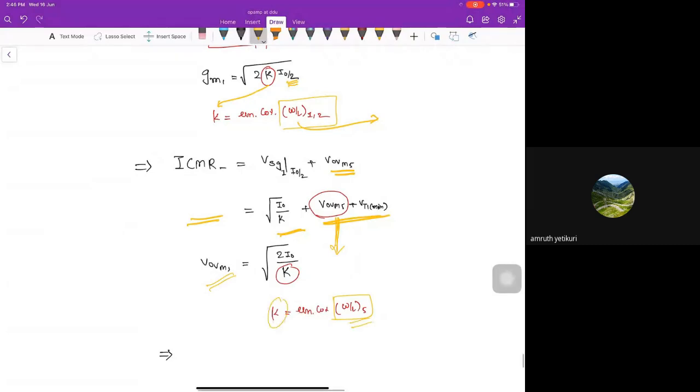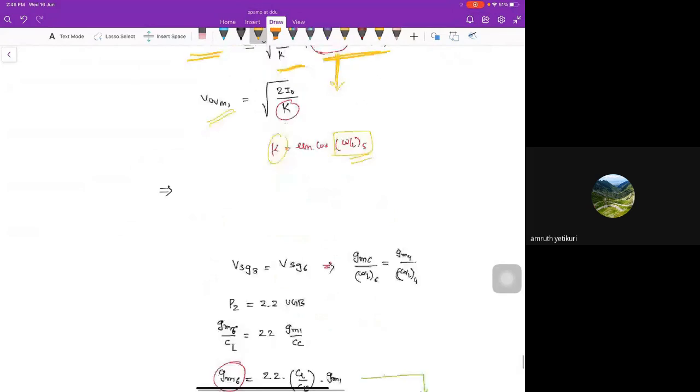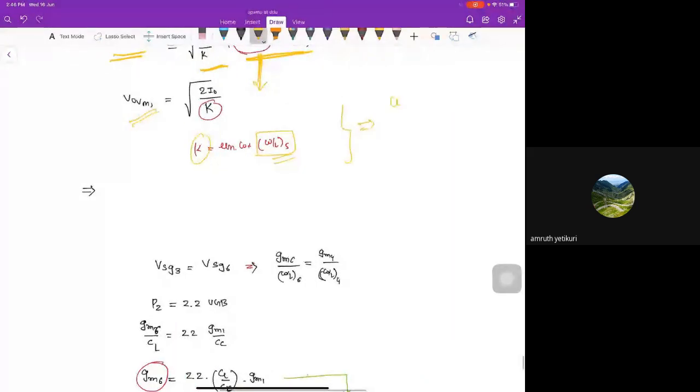Design of the first OTA. See, all these things we have completed, I am telling you, are with approximation, because the real model is a different thing than the square law model. So this is just the approximate value we are getting. After getting this value, putting it into the simulation and running, you will get a mismatch also. So you have to tune that too. Intuitively, you have to know which transistor affects which parameter.